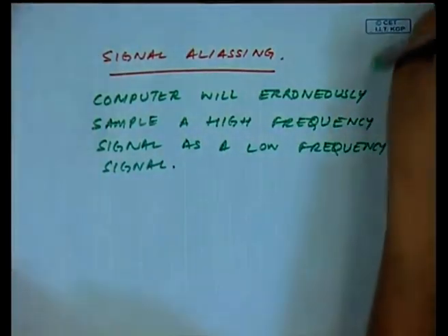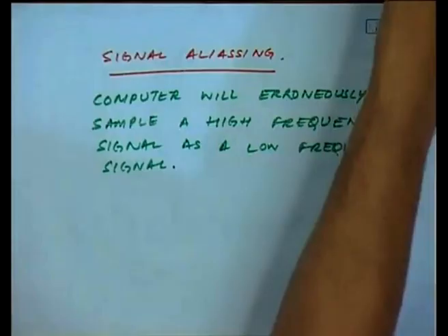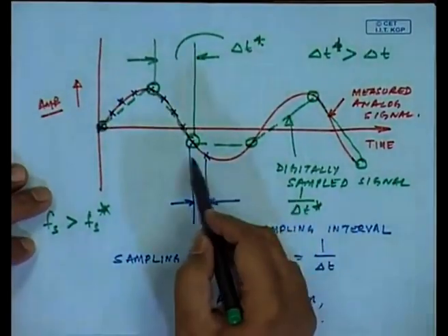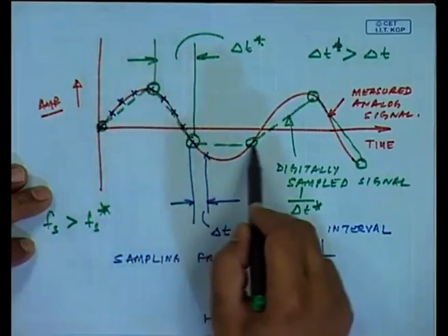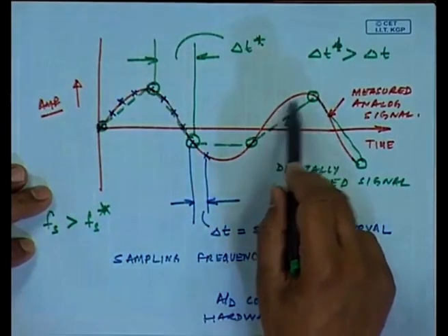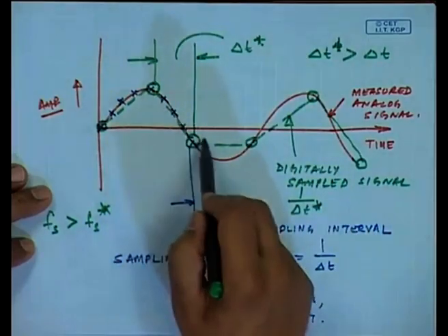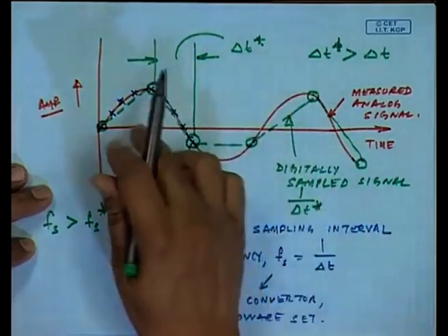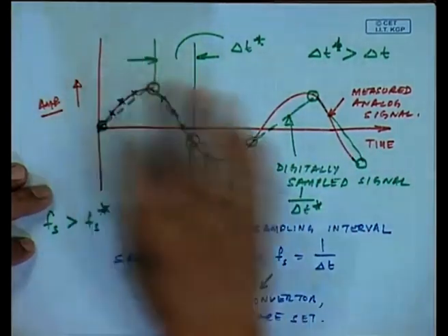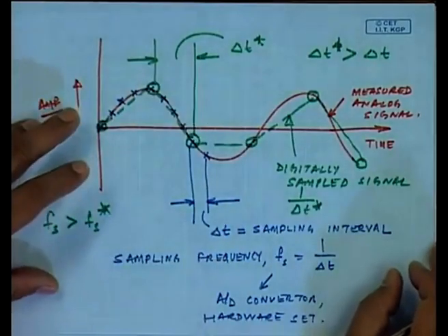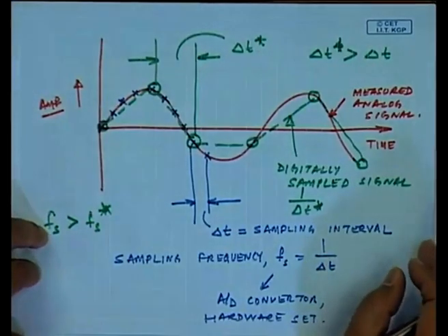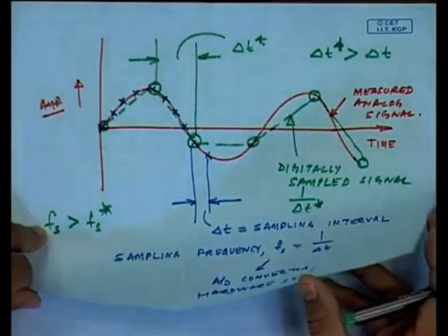Okay. I will go back to the previous example or the figure which I had drawn. If you look here, the original red signal will be misunderstood as a low frequency signal if your sampling is not adequate, and then the FFT will have a lot of low frequency peaks in the frequency domain. So, this has to be avoided. We will be thinking that the sampling frequency whatever the computer has obtained by its sampling is correct, but that cannot be true.